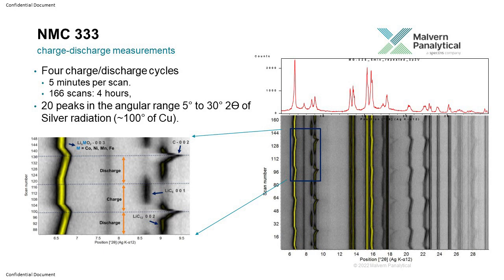If these particles are breathing slowly, expanding and contracting slowly, then nothing will happen. They will not crack. But if this expansion or contraction is very rapid, then it will put a lot of stress onto the particle and then the particle will crack. So you can look into this behavior, whether they are doing expansion and contraction very fast, or doing it slowly.